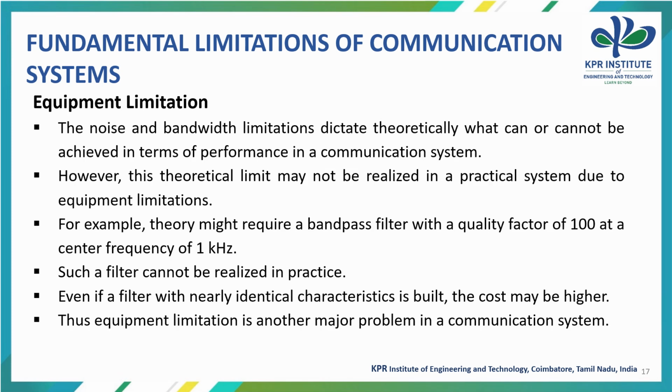Now let's discuss the equipment limitation. The noise and bandwidth limitations dictate theoretically what can and cannot be achieved in terms of performance in the communication system. However, the theoretical limits may not be realized in a practical system due to equipment limitations. For example, theory might require a bandpass filter with a quality factor of 100 at a center frequency of 1 kHz. Such a filter cannot be realized in practice. Even if a filter with nearly identical characteristics is built, the cost may be higher. The equipment limitation is another major concern in any communication system.